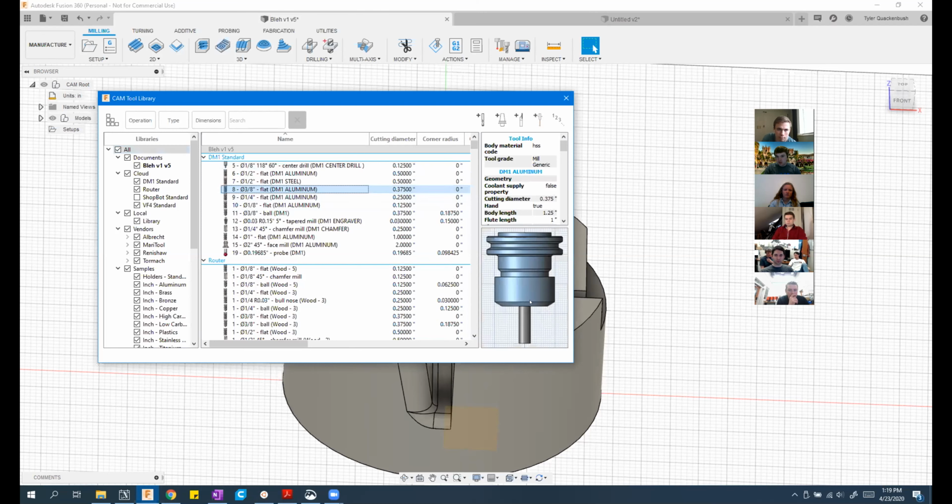So when I come in and look at this, I see it's our 3/8 inch end mill, in a tool holder that looks like this. I think that's an ER collet, or a TG collet. I can check for collisions if I have this stick-out measured right, and the diameter of this right, and all of this information correct. But I don't know how many of us touch the CNCs, but we're all scooting tools in and out.